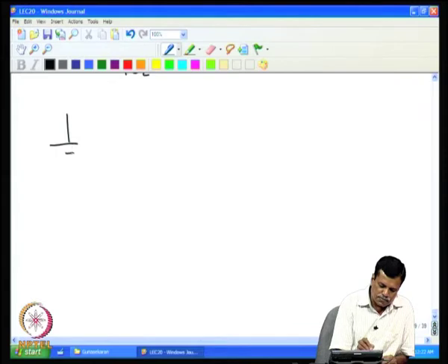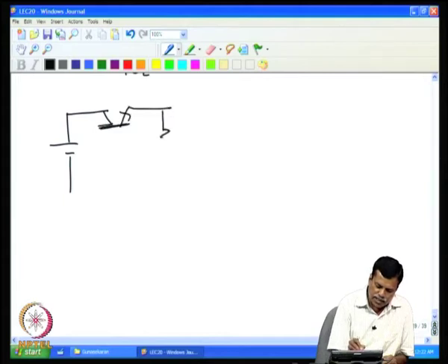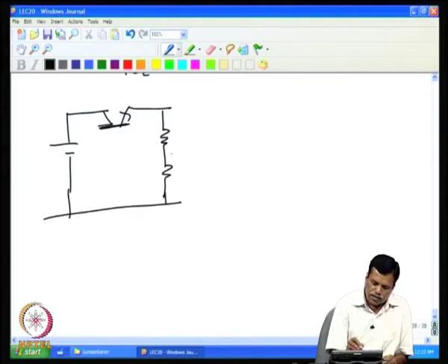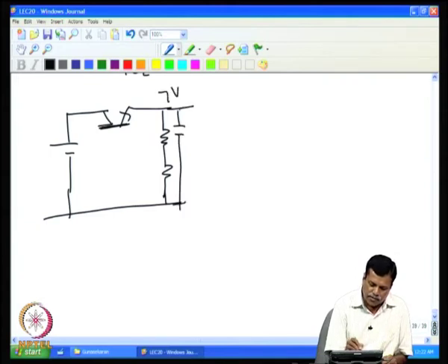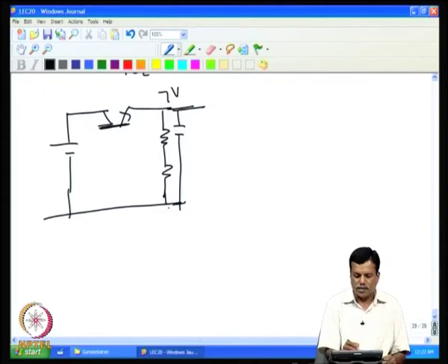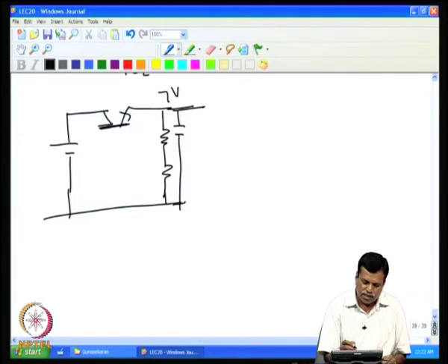So, we will have now voltage source, then we had this regulator here. I will skip the other part of the circuit, I will keep only the output here, and then the regulator output is coming here. So, the other part I skip it here, and you have a regulated output voltage say 7 volt or 8 volt, whatever is required, you can achieve this. Then this is supposed to be given to a Platinum thermometer. So, what we do is we have to make a constant current source.